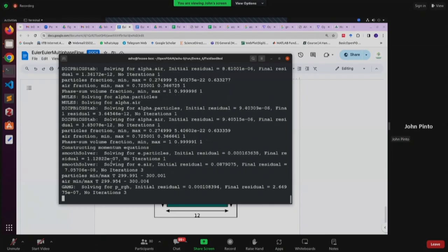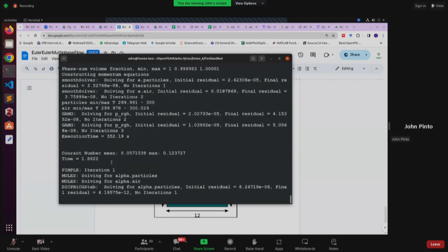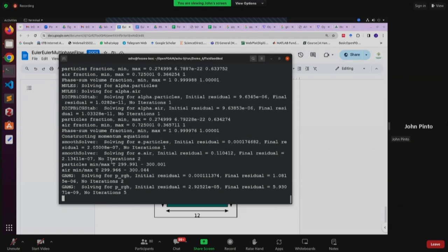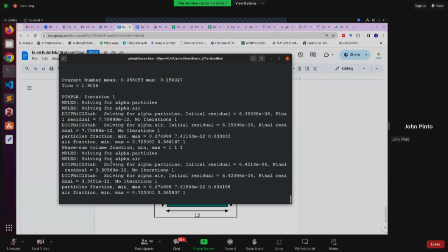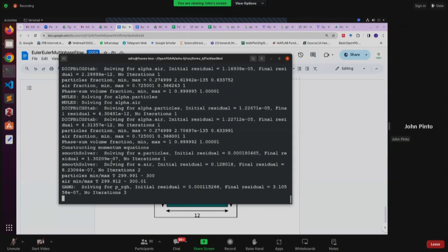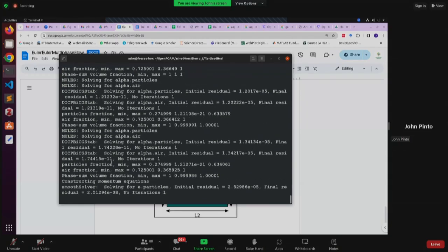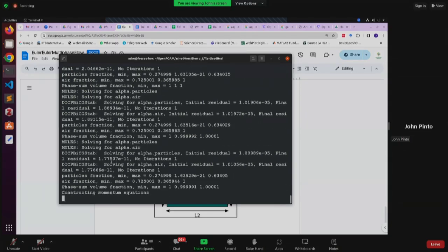Then for the two sides of the wedge, you have to give the boundary condition as cyclic. Then it will simulate as a 2D axisymmetric case, and that will definitely simplify things. Because here we are simulating it as a channel, a vertical slice.